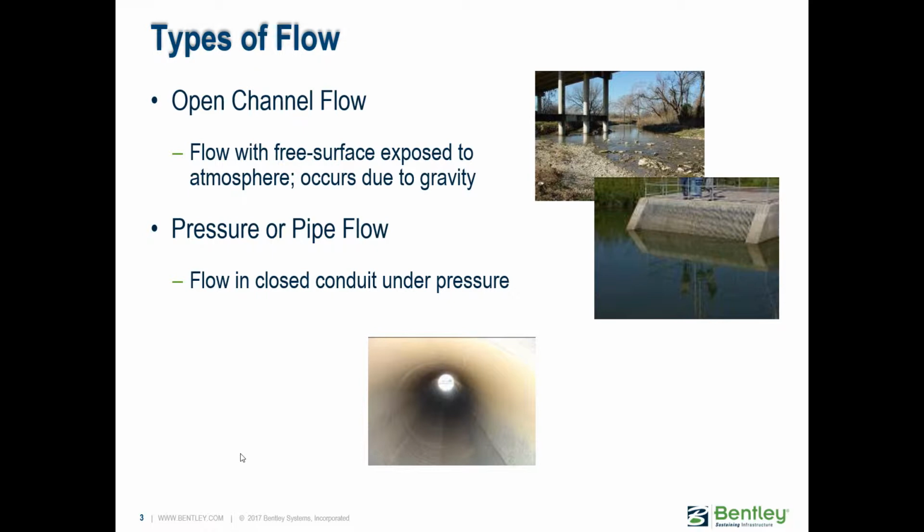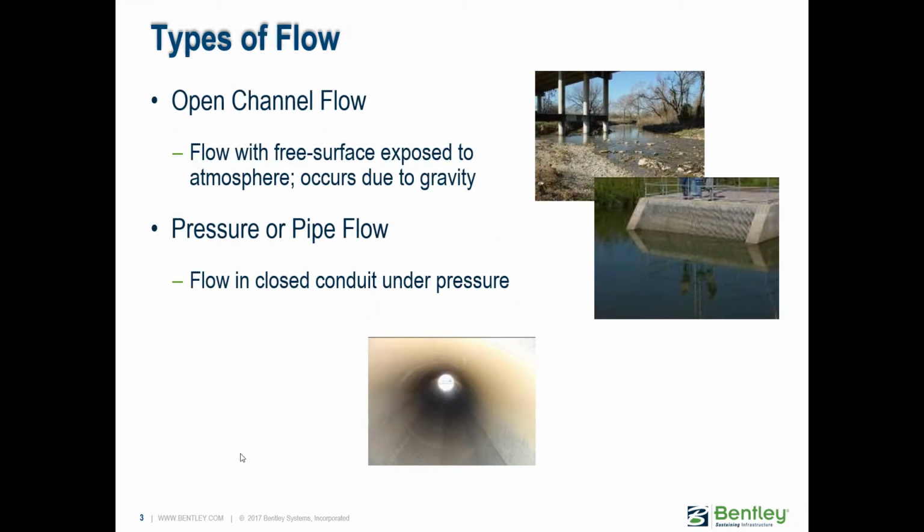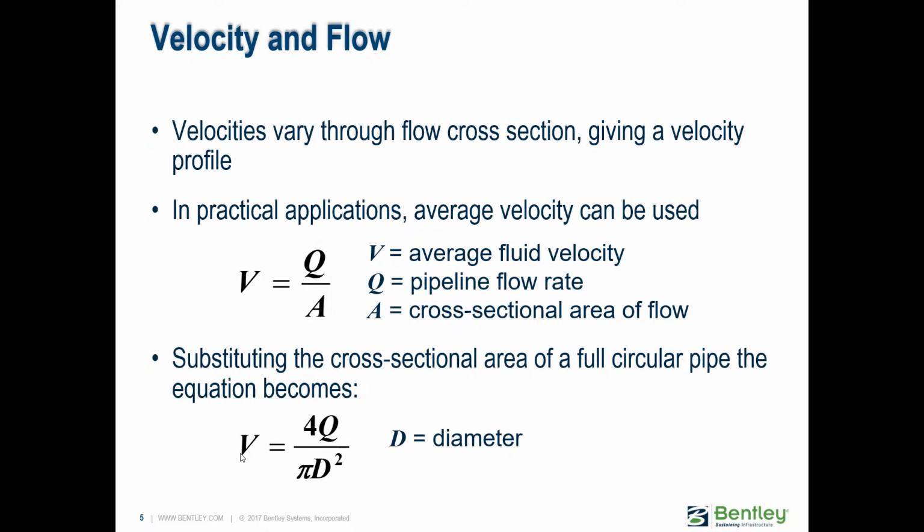You might have also intentionally designed parts of your system to be pressure flow. So it's a flow that is going in a closed pipe like this, and it's under pressure. But for our case, we are going for the open channel flow. So that's what we should keep in mind when we're thinking about StormCAD. Because that's the way that it's supposed to be designed, we use all the hydraulics of open channel flow in StormCAD.